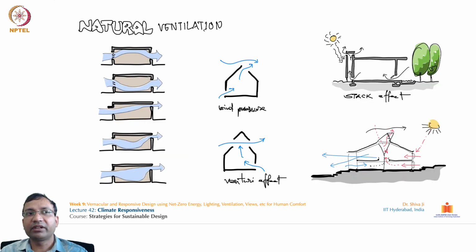Well, some more explanations from a different cross section, like how this hot air can be allowed to exit from the building. This has been done traditionally, as well as in recent times with the recent advances, where it is being done in buildings by using such fins at the top of the structure. So this collects all of the stale air, and it releases the air from this topmost portion in the building.